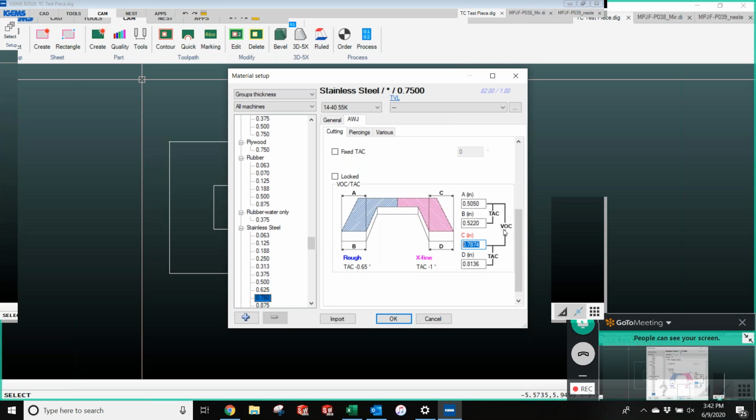So as it cuts slower, it'll actually change the tool offset a little bit to account for the difference in the stream width from the high to the low speeds. So you might measure it, and when it's cutting the slow area, that dimension would probably be a little bit smaller. You might find that it's like 0.502, and then the bottom here might be 0.512.